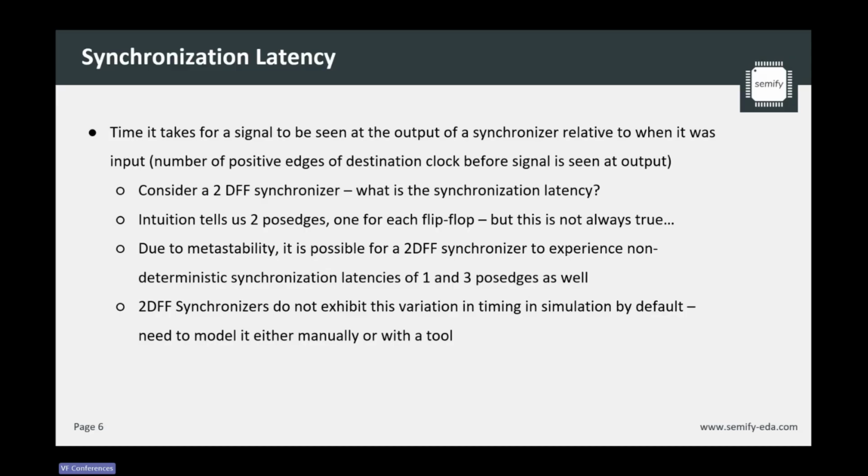And earlier I mentioned this synchronization latency. What I mean by this is that synchronization latency is the time it takes, or rather the number of triggering clock edges it takes for a transition going into a synchronizer to be seen at the output of that synchronizer. And why this is important is because in a regular RTL simulation, the synchronization latency for any 2 flip-flop synchronizer will always be 2 clock cycles. And this is because a regular RTL simulation doesn't really know anything about setup or hold times, and therefore it can't actually model metastability in any way. We need to do this ourselves, and this is where the metastability model comes into play.